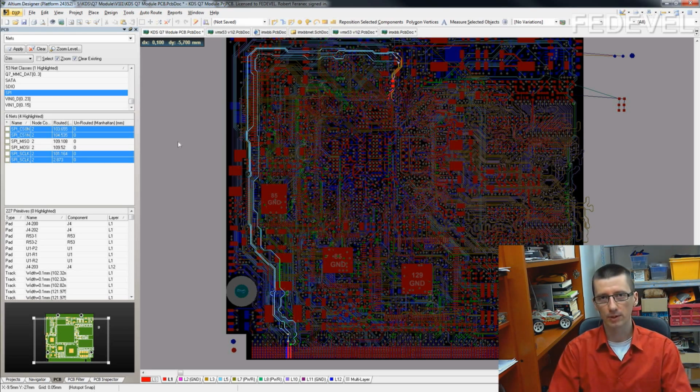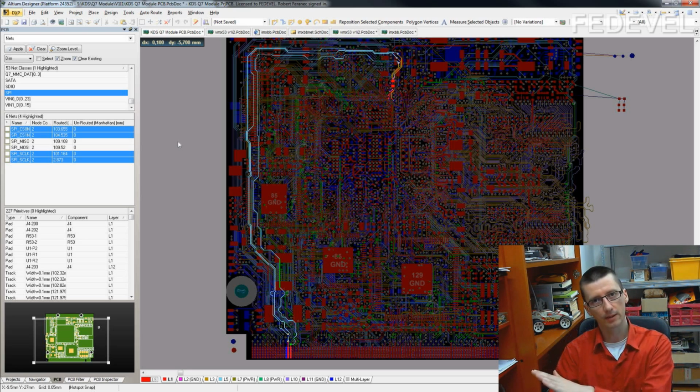One tip when you are doing these local connections, because the PCB is almost done at this stage, the tip is pick up a corner and work systematically. Usually I start from bottom right corner and go through whole PCB systematically. So go to the middle or go to the edge. Why systematically? Because you can clearly see how much you have done and how much needs to be done. It's very important, especially if the layout takes several weeks.